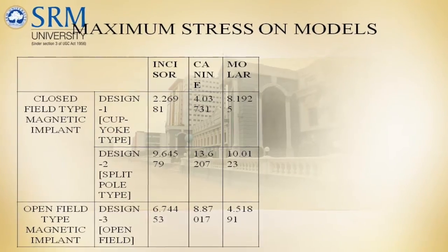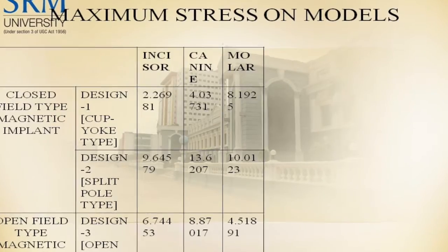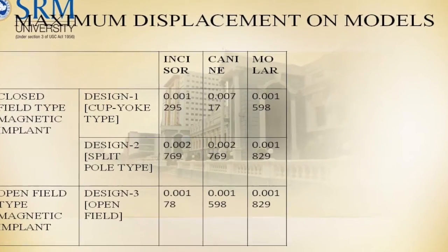Then I did a finite element analysis to find the maximum stress points, and to check whether the maximum stress and the maximum displacement of the model when these forces are applied are fine or not. I realized that the maximum displacement is quite low and within the acceptable region, and the maximum stress also comes within the acceptable region. When doing the individual tooth, I did a little more smoothing and meshing and reduced the stress points, due to which the stress dramatically came down from a 4-digit number to a single-digit number.